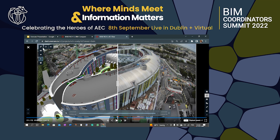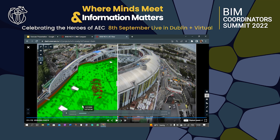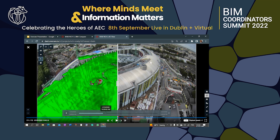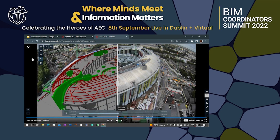So here I have my whole BIM model on top of the camera live view, which allows me to use other functionalities such as a measuring tool in order to measure distances just by clicking on 2 points, for example here. So I can measure distances and I can do a section here as well, and I have my whole timeline that I can play as an animation and stop at any milestone to do the comparison between reality and BIM to track the progress and to track the quality.